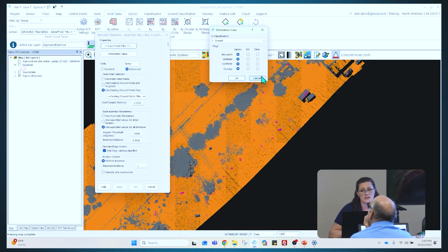All right. If there are no more questions, I believe that is all the material I have for you on these particular topics. As you can see, we can run through them very quickly. So as long as you do not have a humongous data set, you can be done with about an hour and have your full ground classified. And you can actually do an above ground filter, so a height filter, can be used after your ground is classified to classify vegetation, buildings, or anything of that nature.